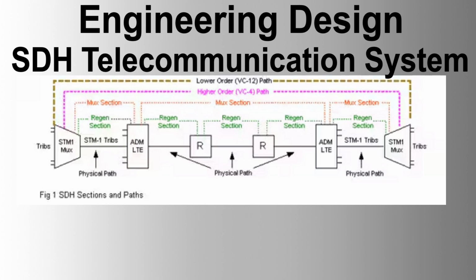Telecommunication system. Primary function. The primary function of the fiber optic telecommunication system is to facilitate the operation of the SCADA system to allow safe and efficient operation of the pipeline and the facilities with the minimum of manned intervention. Operation. The design of the telecom system shall be based on a 24-hour per day, 365 days a year operation from all manned and unmanned locations of the pipeline.